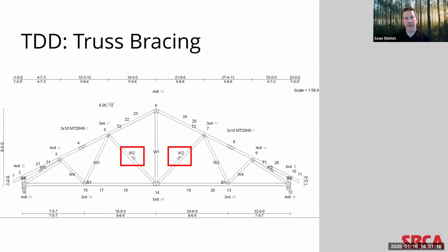I didn't have a truss design drawing showing this, but sometimes you will also see web reinforcement also called out similar to this on the truss design drawings. And that will typically show a 2x4, 2x6 member affixed to one of these webs along its length.